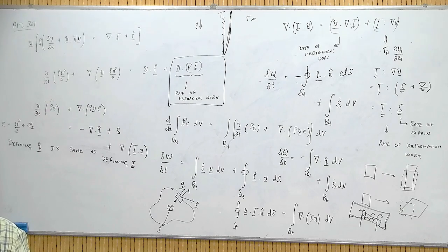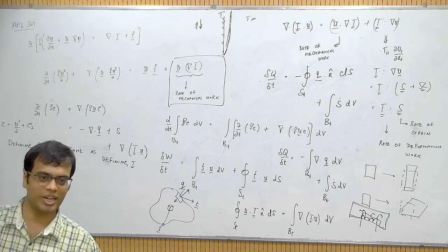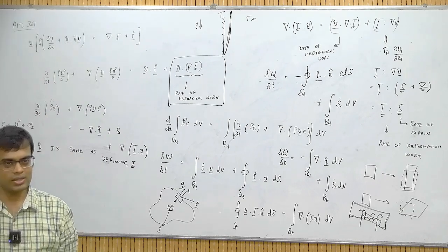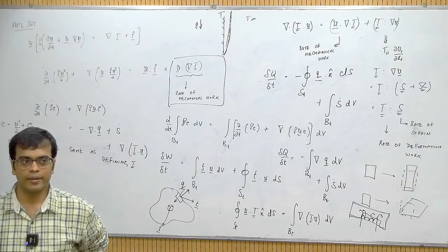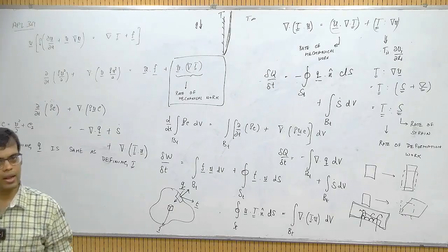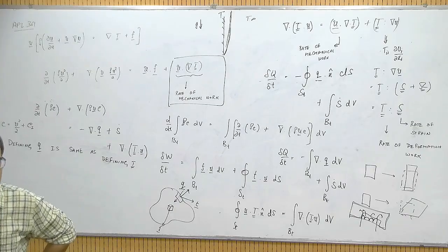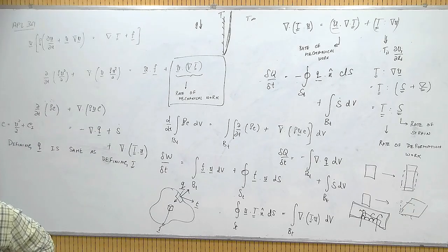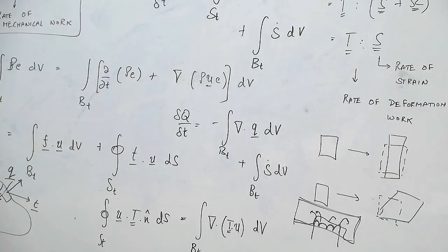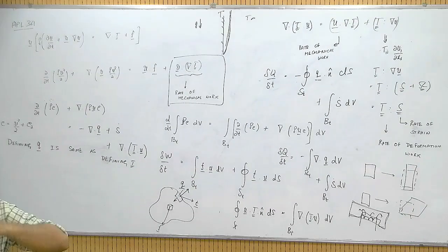By what physical picture do you expect some traction vector on that isolated blob of air? Okay, let's say there's some pressure of air. You said viscosity. Okay, all of these are due to what? When you are zooming in inside the fluid, what is the physical mechanism of both pressure and viscosity? This is the rate of transfer of momentum due to vibrating particles.